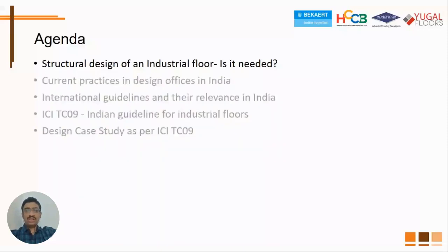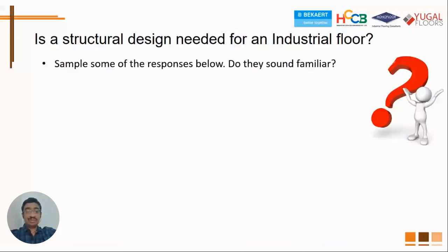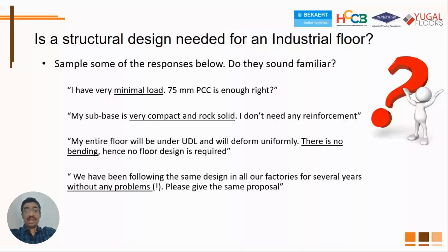Now, the question is whether structural design is needed for an industrial floor. If you just ask anybody in the industry, a lot of times you get these kinds of qualitative responses. For example, people could come up to you and say, I have very minimal load, can I just provide 75 or 100 PCC? My sub base is very compact and rock solid, so do I need any reinforcement? My entire floor will be under UDL and it will deform uniformly, so there is no bending. Why is a floor design needed? And this is a very typical one, the last one: I have used the same design in all my factories for several years without any problems. Please give me the same proposal.